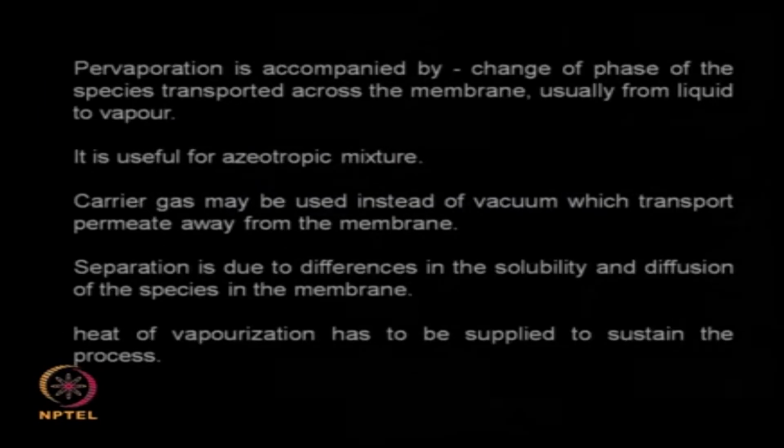So in pervaporation there is always a change of phase. Initially you have the liquid, then it goes into vapor, then after diffusion this vapor again goes back into liquid. So there is a change of phase. It is very useful for azeotropic mixtures.